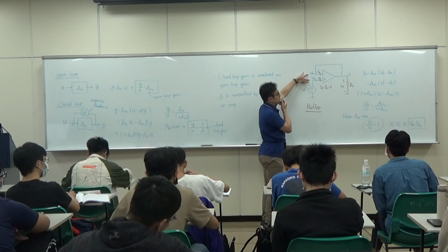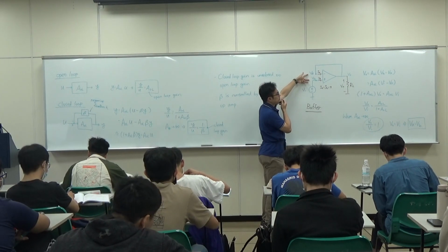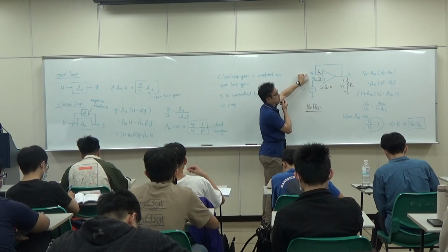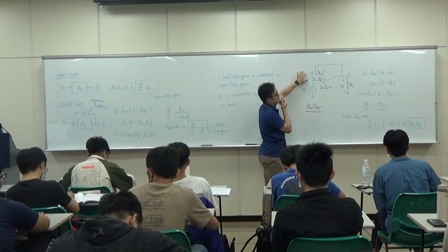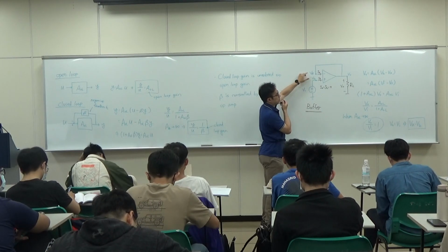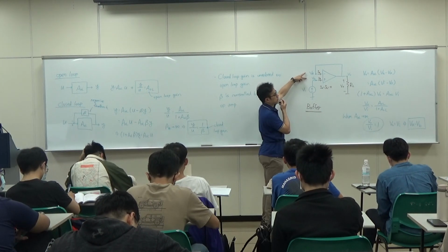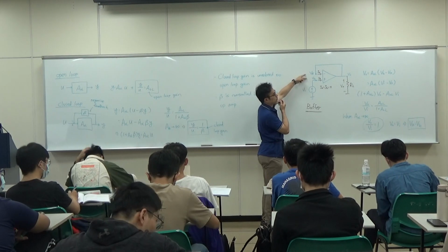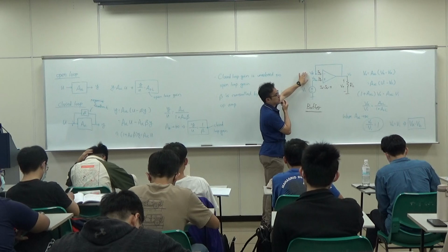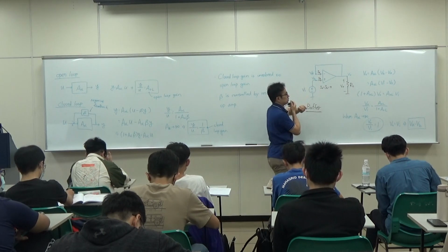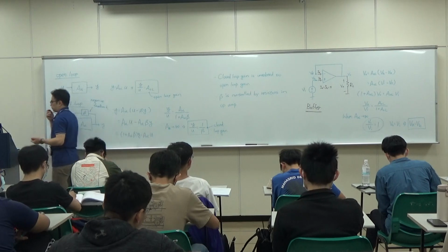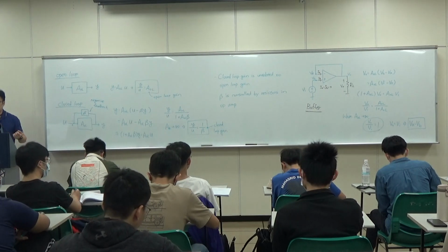Because one major function of the operational amplifier is to amplify the voltage difference, and because a thermocouple has two output voltages, we need to compare the difference of those two outputs. So that's why it is designed this way. It amplifies the difference of two voltages.